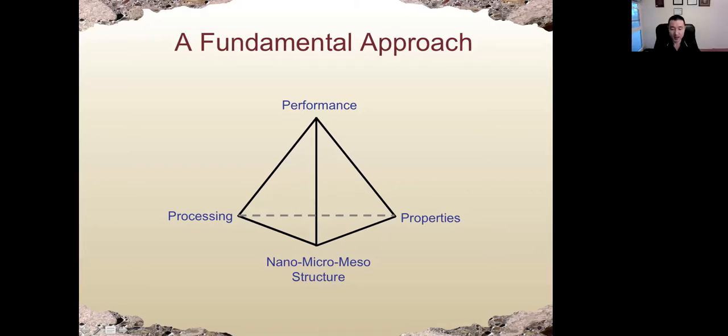And we should also focus on the nano and microstructure of the materials. We can use chemical analysis or XRD, which is X-ray diffraction, and scanning electron microscope to study the chemical reaction as well as the microstructure of the matrix.